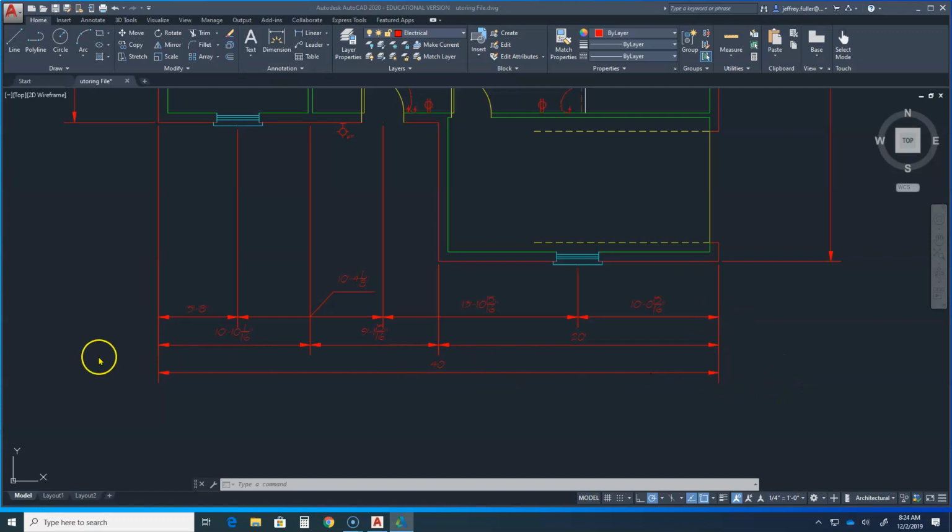So this line, the one I'm circling with my cursor, is the 8-foot line, and it tells you the overall dimension of the front of the structure. Right here it's 40 feet from left to right. The next line, which is the 6-foot line, is 6 feet from the furthest point of the structure, and that one tells us what our major wall measurements are.